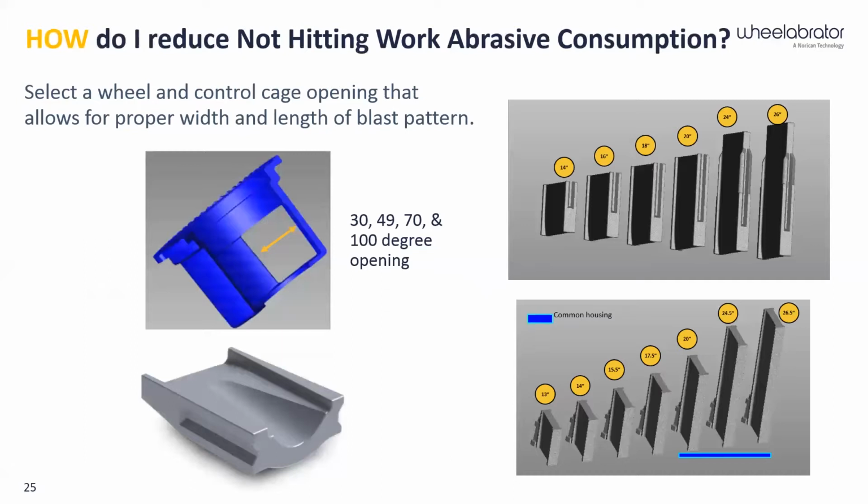Down at the bottom, you'll see a picture indicative of what's called a concave blade. It funnels your pattern in. Obviously, it has to be the right application, like a rod or bar machine. It's only 1/2-inch diameter. Why do I want a 2.5 or 3.5-inch wide pattern when I'm only blasting a 1/2-inch wide part? So try to funnel that abrasive in so that it's not missing my part, using up abrasive and wearing components out. We try to minimize that as best we can.